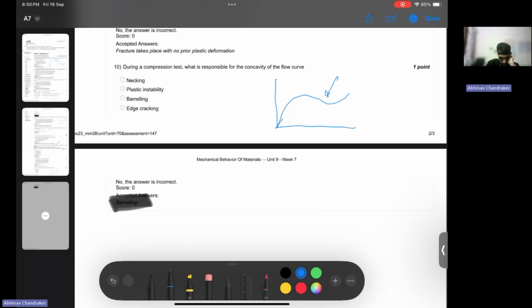That I think is due to barreling because it becomes easier for it, instead of having longitudinal strain, to just have transverse strain in particular cross sections only, not overall throughout the sample. So that is easier than uniform straining, I think, this kind of barreling. So what happens is in the middle you have very high stresses, while on the sides you have lower stress.